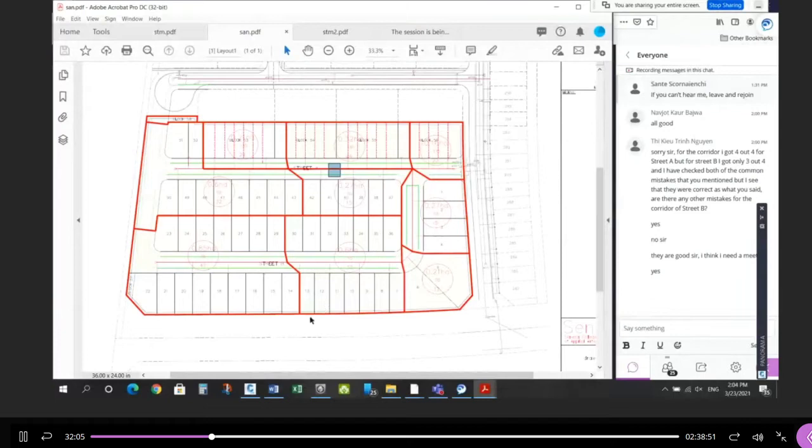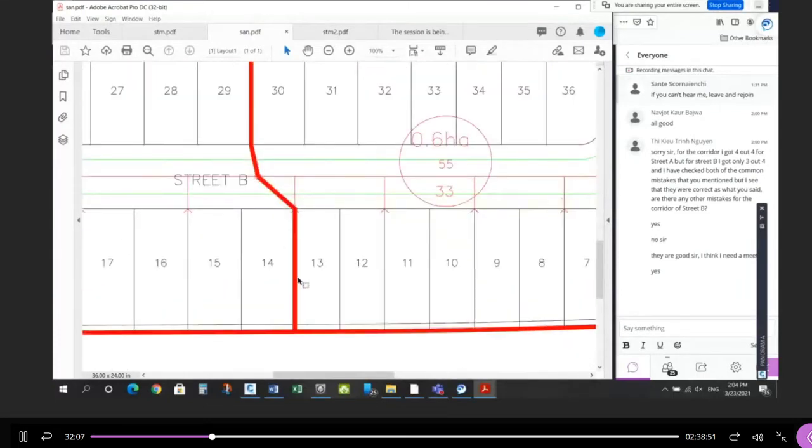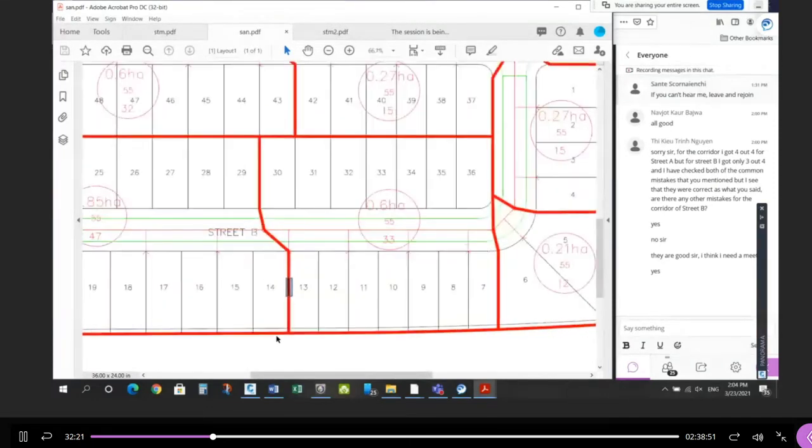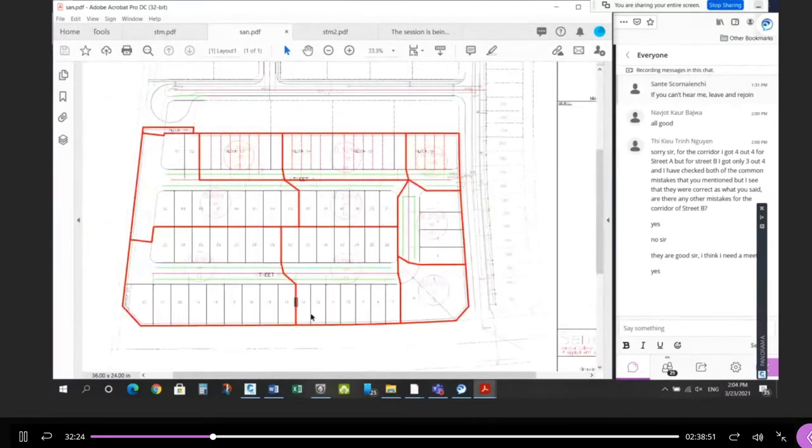Did you draw the division lines in the right spot? Here's another error down here, right? This line should actually be here because these 2 units drain through this pipe connecting to this pipe. So this line should be from here to here and then down this unit. So this is drawn in the wrong spot. Okay. Otherwise, it's not bad. At a glance, it looks good.